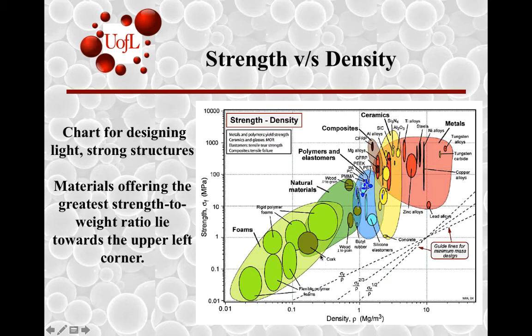So anything as this gets maximized, if you draw a line parallel to this, you will be able to select, depending upon the yield sigma by rho metric based on L and F, you will see different options that are screened off below the line and different options that are compelling alternatives if they fall above the line.